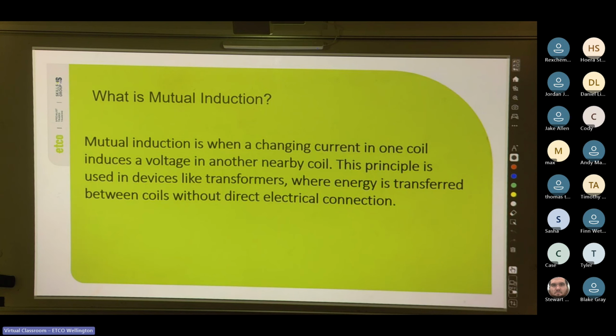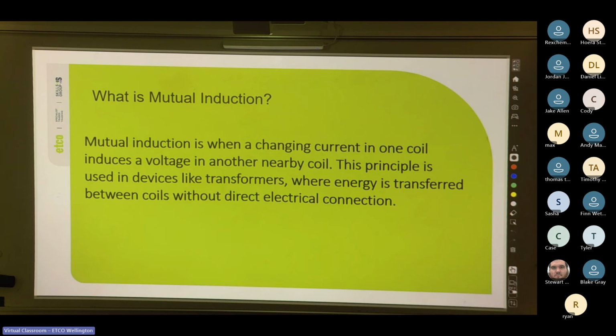But yeah, we just need to be aware of these ideas of magnetism because they do play a part, especially when it comes to everyday things like transformers. Like there are small transformers inside the power packs for your laptops or inside the devices you use to charge your phone. So if you think about that USB port in the PowerPoints, there's a little tiny transformer in there that steps down the voltage before it changes it to DC. Yep, current transformers, or CTs, which we use for monitoring power usage or current usage. Yep, good answers, guys. Cool.